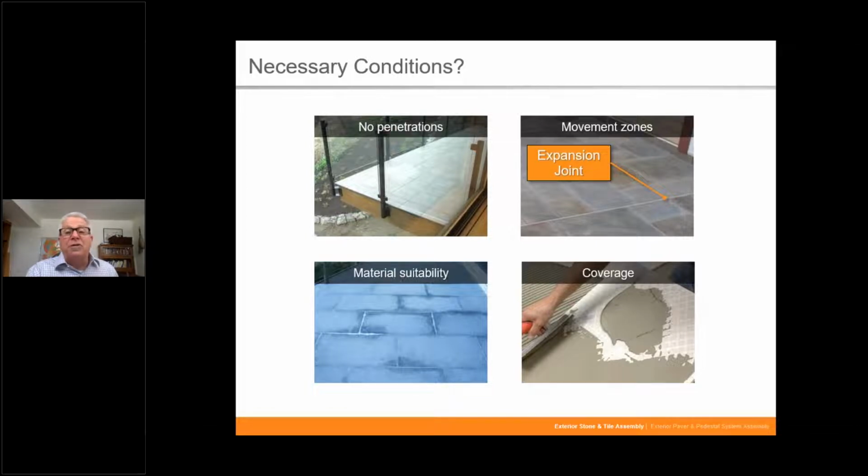And if it's going to be a natural stone, 0.5% moisture content, which you start looking for natural stones that have that low absorption rate, you're going to be limited in your selections. But still, those materials, the bond coat, the grout, anything that you introduce into this assembly, we should look at the suitability. Is it going to work in that environment?